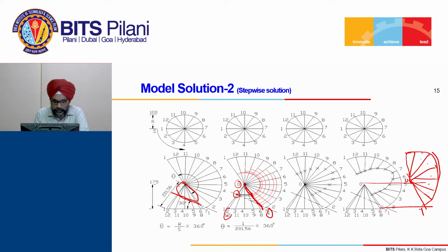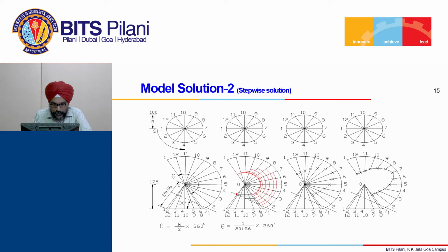Note that 2 and 12 are coincident points in the front view. That is why the corresponding point is here. So, that is transferred on O2. How is it transferred? You can see for transferring the point on O1, simply we had to move it and you get the point, and after that you draw the arc here and you reach this point also.